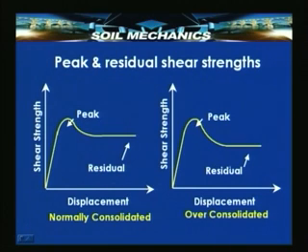There is a peak and then a residual value, but what is obvious from these two figures is that when the soil is over consolidated, the fall to residual is much more. After reaching the peak, the drop in shear strength is much more with displacement in over consolidated clays.